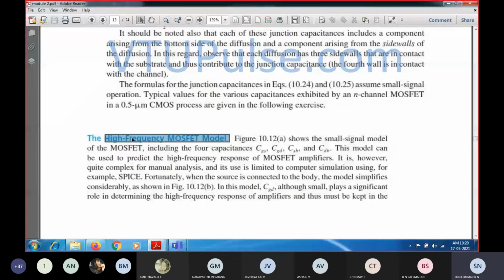So these internal MOSFET capacitances will not have any impact on the output characteristics of the MOSFET, that is, on the current or the threshold voltage. It is not going to impact the current or voltage characteristics. So because of that, the gain was at its maximum.